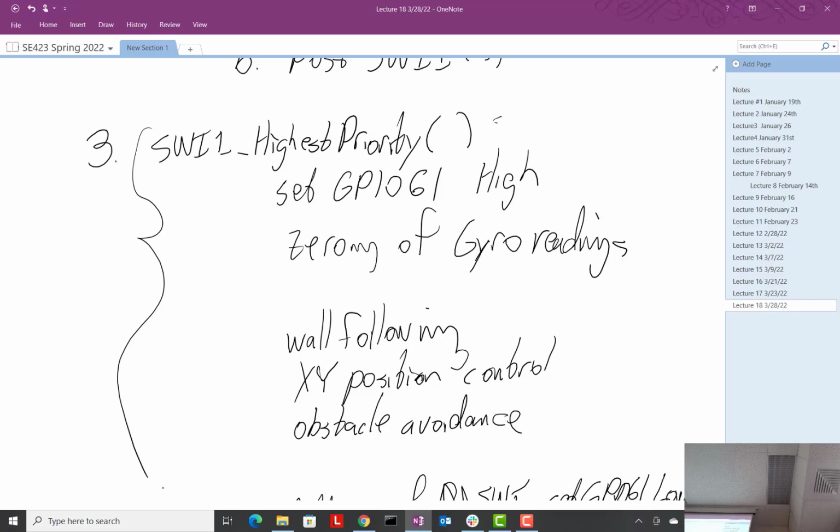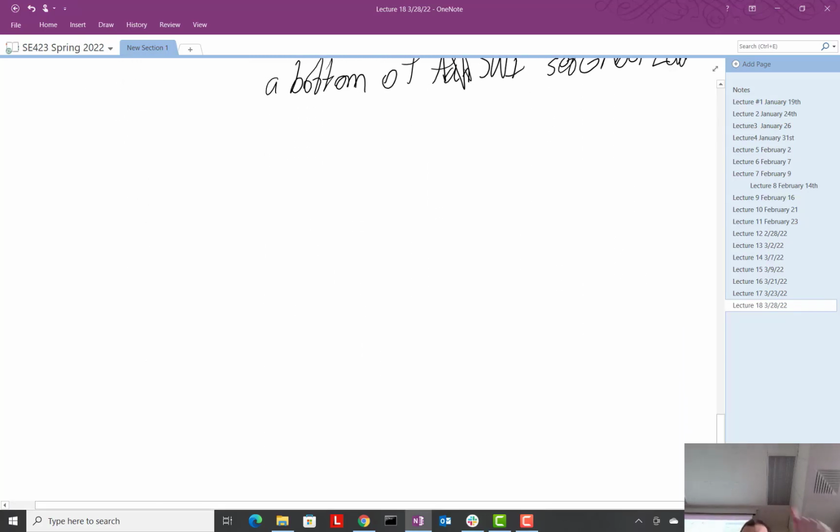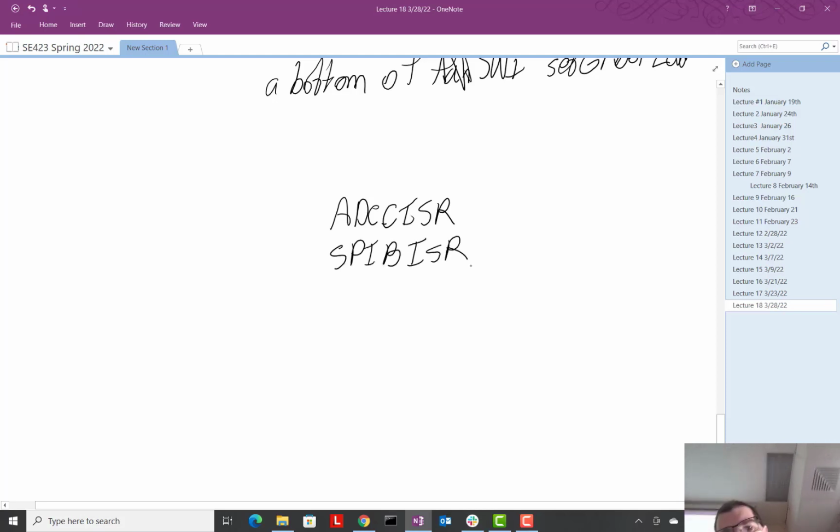What's our issue? Okay, let's think about this. Why do we need to put it in a software interrupt? Okay, let's think about all the interrupts that are happening on this processor. So we just talked about two. We've got ADC ISR. We've got the SPI ISR. Now, these two are in order.